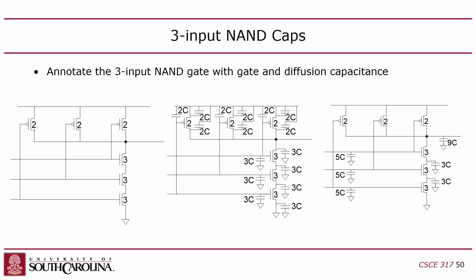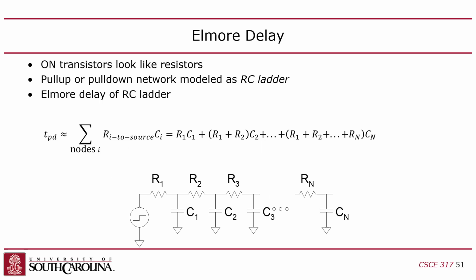branching paths where you have a wire that goes to a resistor and then a capacitor that goes to ground or VDD, but then another resistor and then another capacitor, right? You have a circuit where you've got lumps, right? You've got segments, right? With multiple resistors that are dividing up the circuit, essentially, right? So you have to use this approach called Elmore delay. Okay, so the Elmore delay it's a really simple idea.